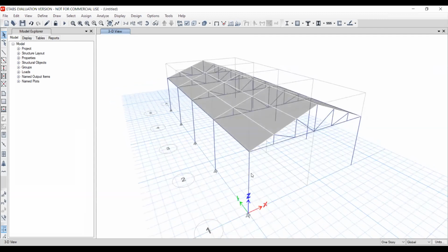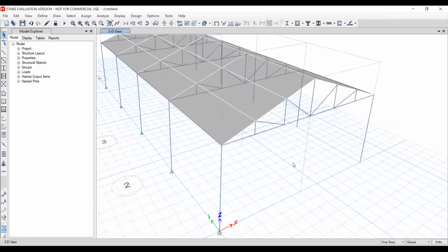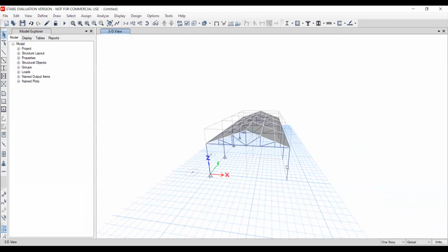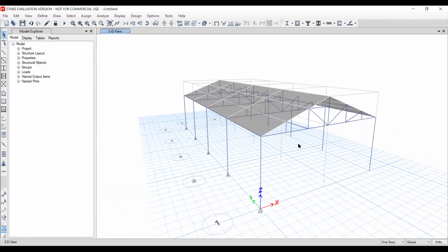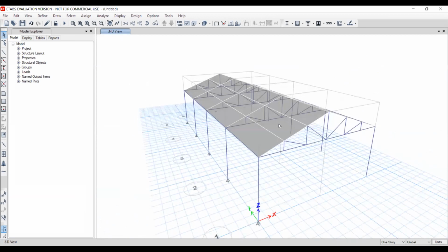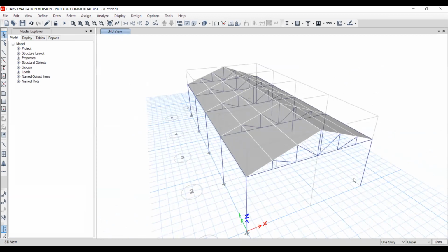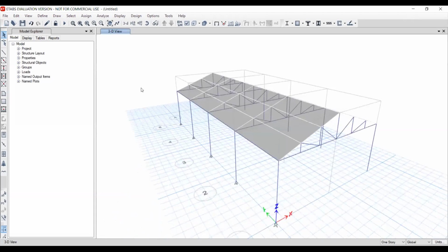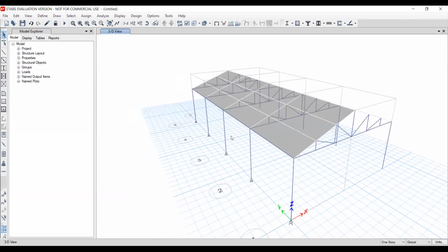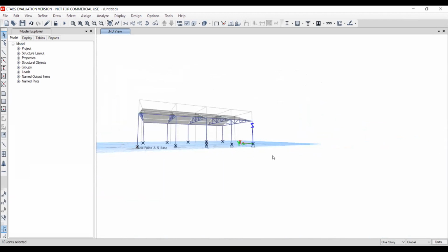These are the column members, and these are the other column members. So now the geometry part is completed. Now we have to apply the loads on these trusses, on this shape, on this floor, where here we do not give the supports over here. So generally they are all pin connections. So select all the members, select all the bottom floor members like this.